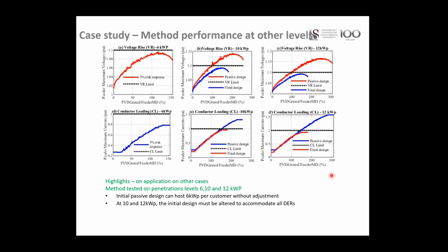So I think that's where the biggest issue comes in, and you are still required to have a capability to control that voltage, such that when the sun or whatever is being used is no longer there, you can still support the voltage when it's low, and pull it down when it's high.